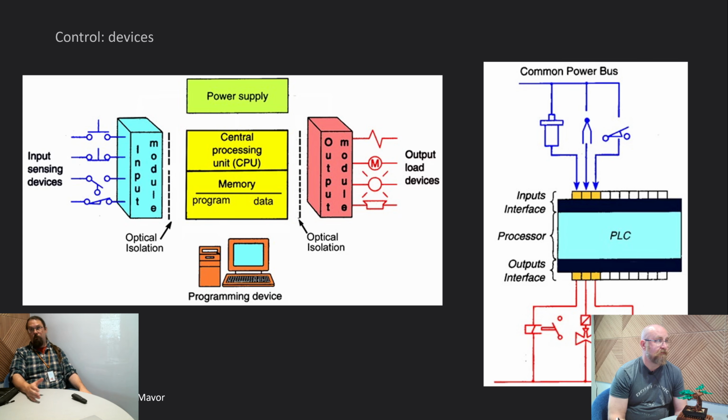A relay output module is typically capable of switching 120 or 240 volt power directly, whereas a regular digital or signal output module will only output a discrete 24-volt signal, with a very small amount of current being capable of being driven by that output. But we'll talk about that in more detail as we go through things.